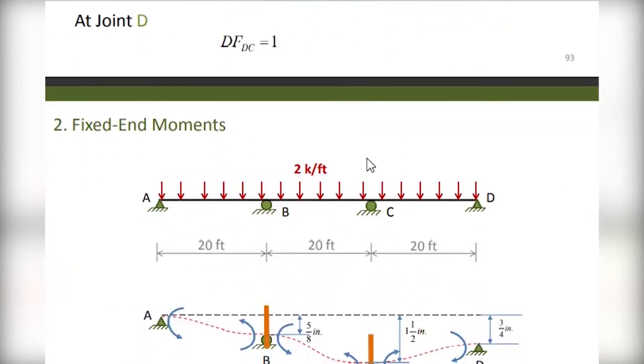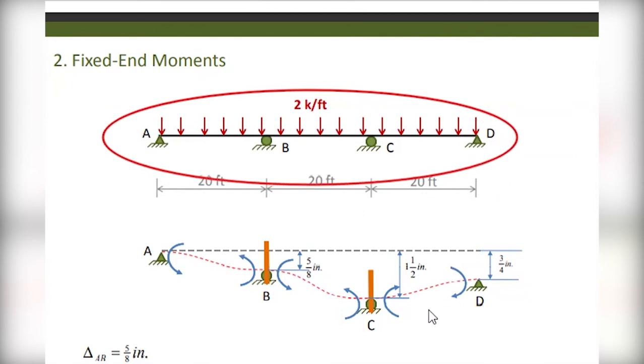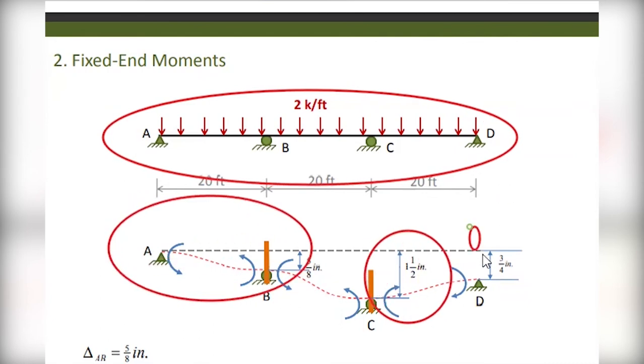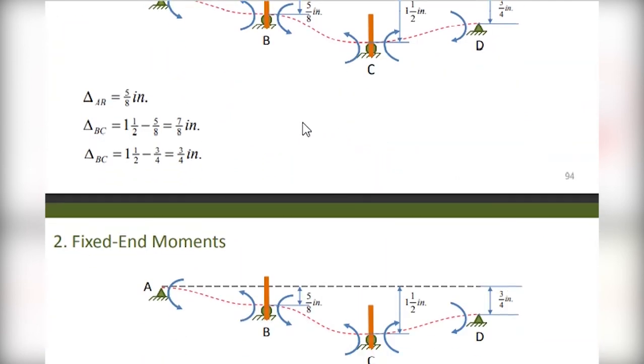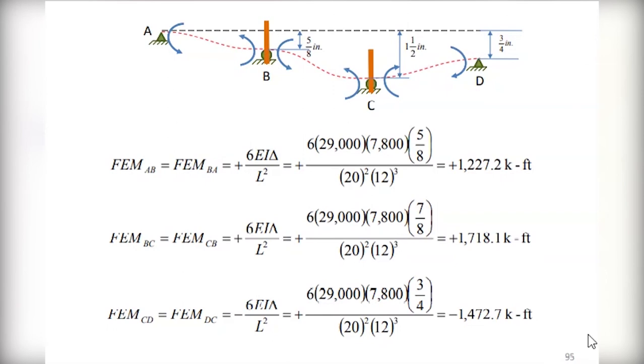So on proceeding, the normal way, find the fixed end moment as a normal procedure. The fixed end moment can be calculated depending on the fixed conditions. So carry on by looking at the formula for the support on each member or each span. After having that, the end condition should also be considered with the deflection. If one support is settled, the deflection also should be considered. So the value is in empirical, so you can have the displacement there. So look at that one. After that, you can proceed. You add the value to the fixed end moment by considering a slope deflection with consideration of the support C. It is settled.